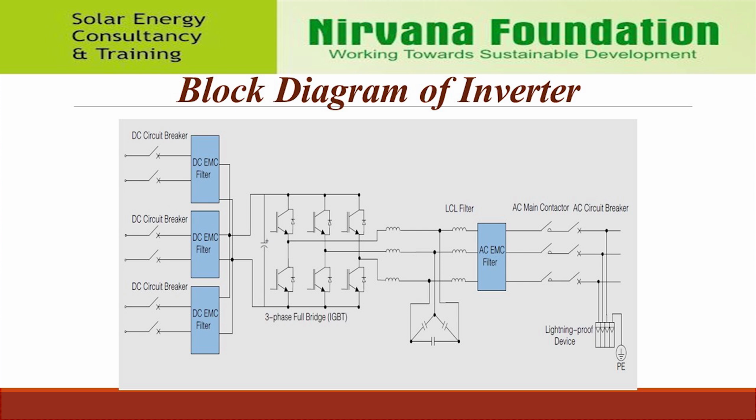AC circuit breaker. DC side of the inverter in photovoltaic systems and other DC systems. MPP, maximum power point, trackers generate disturbances into both the grid's AC power line, as well as the DC side of the solar module. An AC filter is typically used on the grid's AC power line, but the noise generated on the DC side tends to be overlooked.